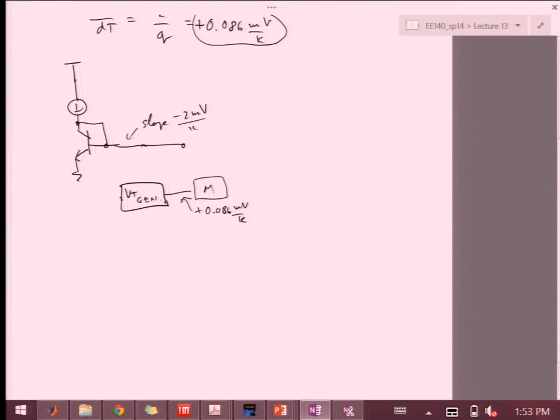Then I'll multiply this up with some, let me draw the amplifier shape just so. And then I'll add the two together and get Vout with slope that's approximately 0. So Vout will be equal to my VBE plus M times VT, where M is some gain. It's a fixed factor, 5, 10, we'll see. Okay.